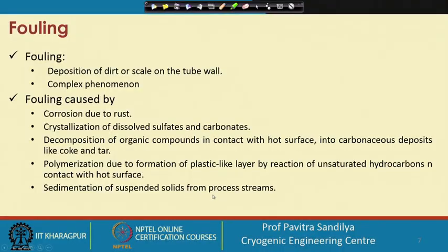And then we could have sedimentation of the suspended solids from the process streams, and later we can have some biological activity due to some algae or bacteria that may be there in the fluid streams. So all these things may cause some kind of fouling resistance.